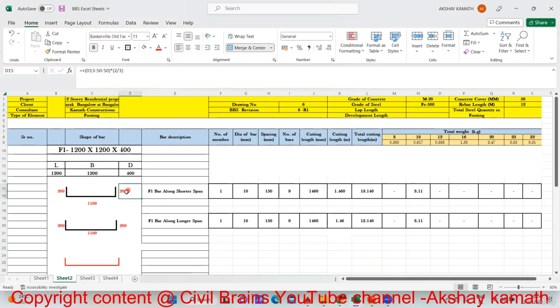Also this depth, whatever I've taken, that is 200 and 200, here we'll not put 2/3 and 2/3. That also we will do, because I'll teach you all the methods, and then it depends totally on you what you want to follow. Few people don't do 2/3 here. They directly take overall depth minus top cover and bottom cover, and that will be the L. In that case, we need to take out this 2/3. But in most construction practices we usually take 67% of that value, so that is why I've written 2/3. If you don't want to do that, you strike out this 2/3 from there. Similarly, your answer is going to change.